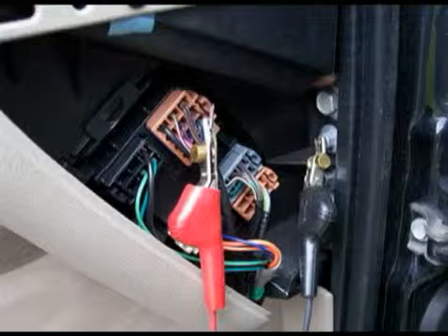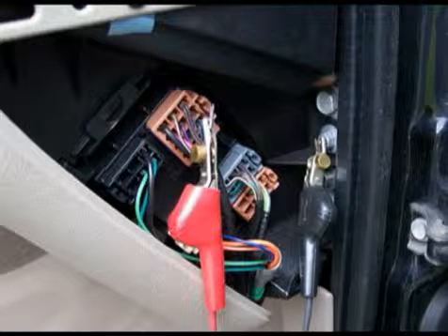We've learned through our diagnosis and our wiring diagram that there is access to connectors on the end of the instrument panel on the passenger side. We remove the small cover and we access the wires between the control head and the blower motor control module.